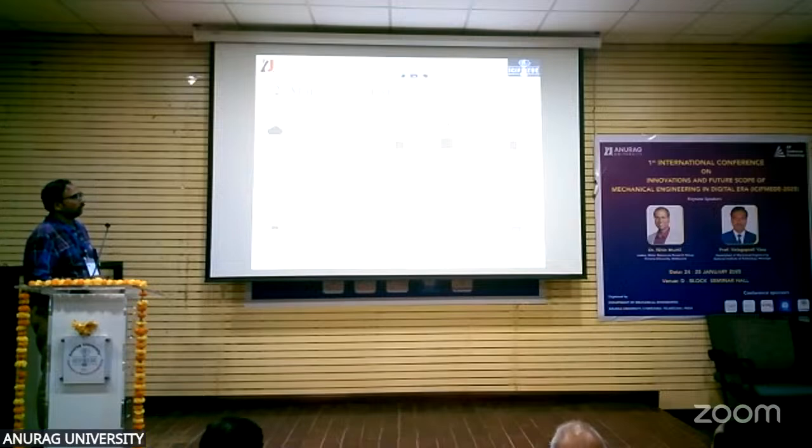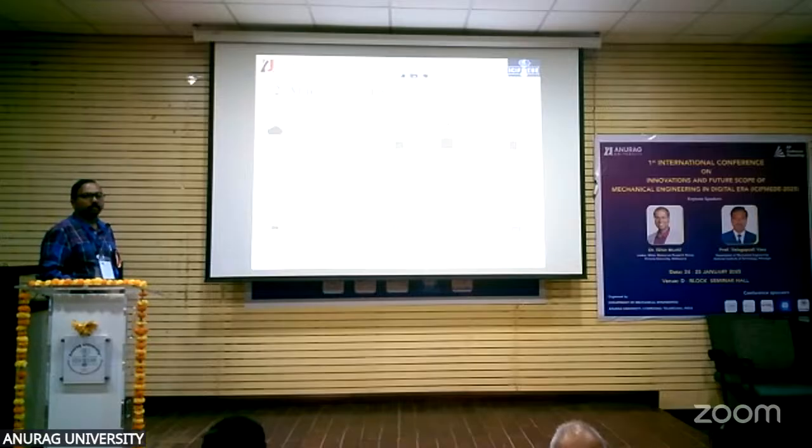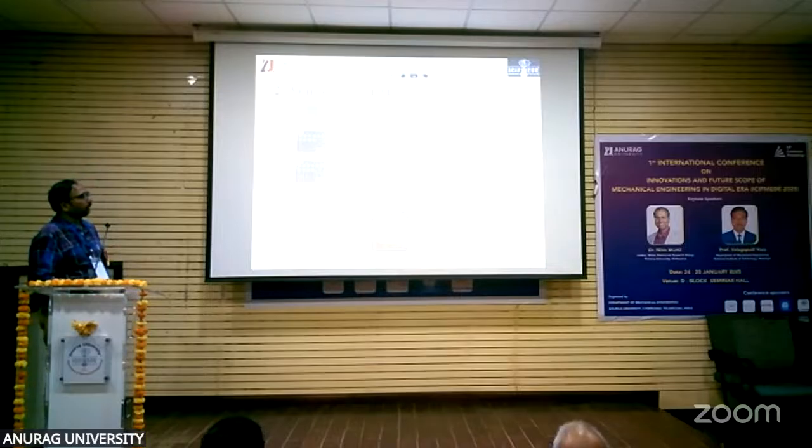Once the laminate has been formed, it is cut to 100 mm by 80 mm with a thickness of 7 mm. Around 8 layers of glass fibers have been placed at an orientation of 0 and 90 degrees. Once the laminate is formed, it is drilled. The drilling parameters are the MWCNT composition, cutting speed, and feed rate. With the Taguchi method orthogonal array, the drilling operation has been done.